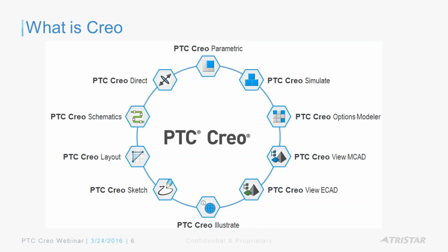You can just install Creo Simulate separately, so you're not using the Creo Parametric app or the Creo license itself while doing the analysis. You could use it licensed when you run a what-if scenario or optimization studies, but you do have the option to just run a standalone simulation app instead of running it in the integrated mode.